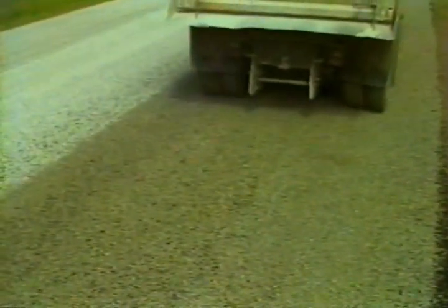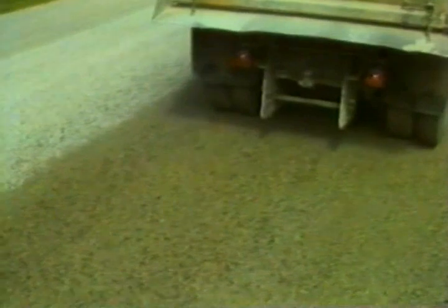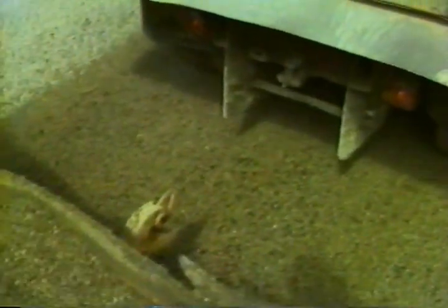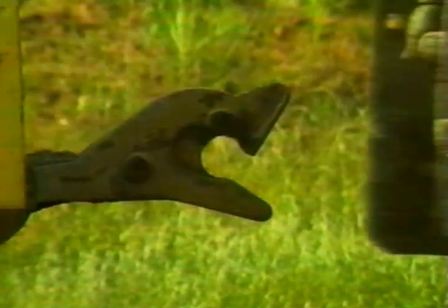Big spills, on the other hand, can happen if the chipper and dump truck disengage during spreading. While this machine's hitch is designed to prevent disengagement, many chippers have a simple hook that doesn't completely surround the steel rod connection of the truck. Should the chipper operator fail to verify the connection, the entire load could be dumped when the chipper pulls away.